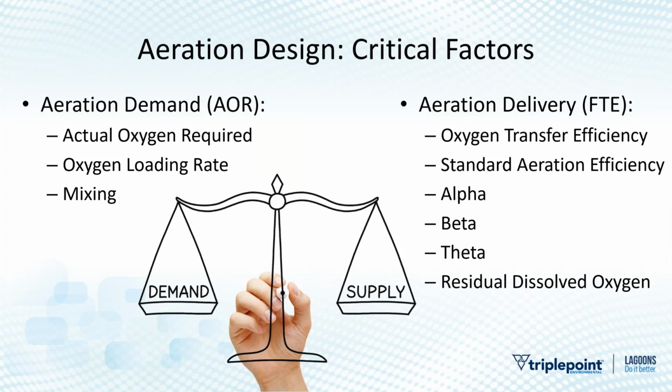If your lagoon has a water volume, it's got bacteria, it's got loading, and those bacteria want to breathe. We're not making them treat anything. We're just providing them the oxygen such that they can treat the wastewater. If we don't provide enough to meet their demand, they might go anoxic, they might go dormant, they might not work, you might get odors in your lagoon.